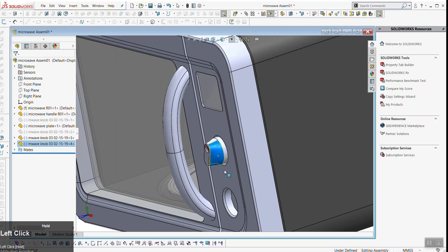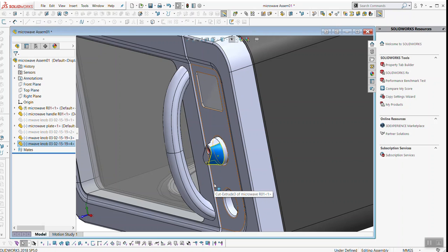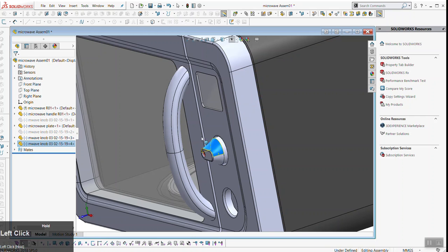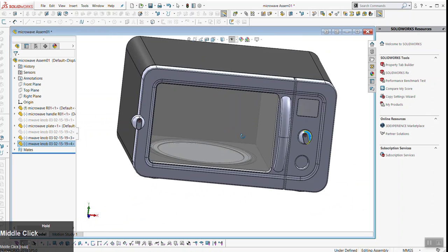I can't drag it out. However, the nice thing is because of the concentric mate, it can spin. There's nothing fixing it vertically. That's the relationship it has. It's saying, take these two circles and make them parallel. Parallel is not the right term. Concentric is the equivalent, but I think that's making a point. So through the way that you mate your objects, you can make it so that things easily move and turn and change, okay? Are there any questions on any of that?